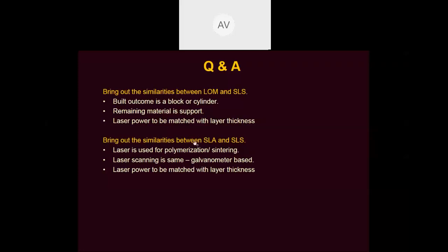And the similarities between SLA and SLS: the laser is used for polymerization and sintering. Laser scanning is the same, galvanometer based. And the laser power is to be matched with the layer thickness.